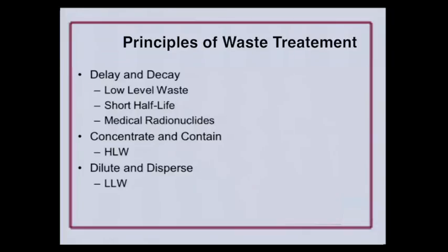In this case, what is in the process of being done is removal of the strontium and the cesium from it, and then processing it on out as salt waste. And then the strontium, cesium, and the other sludge components are taken through the vitrification process, where they're evaporated down, concentrated, and then mixed with glass for encapsulation.